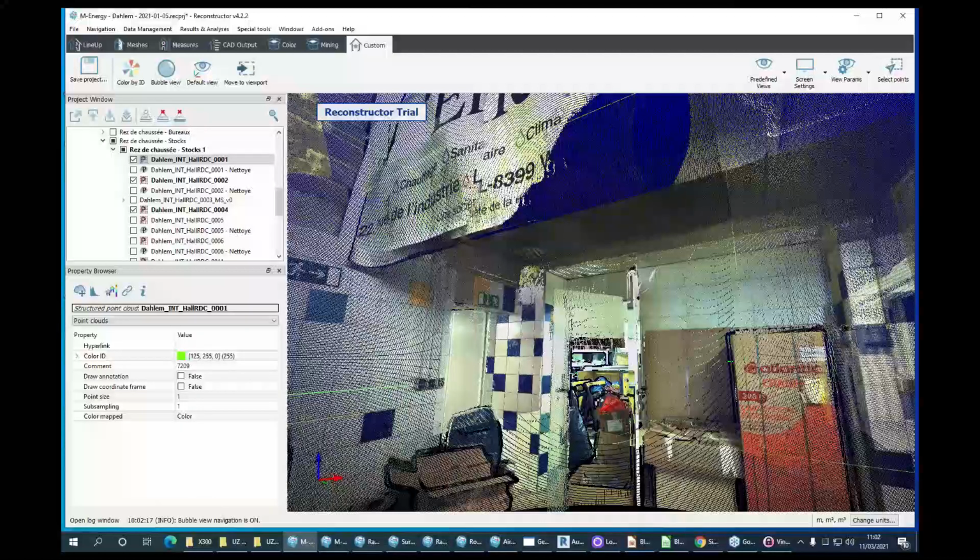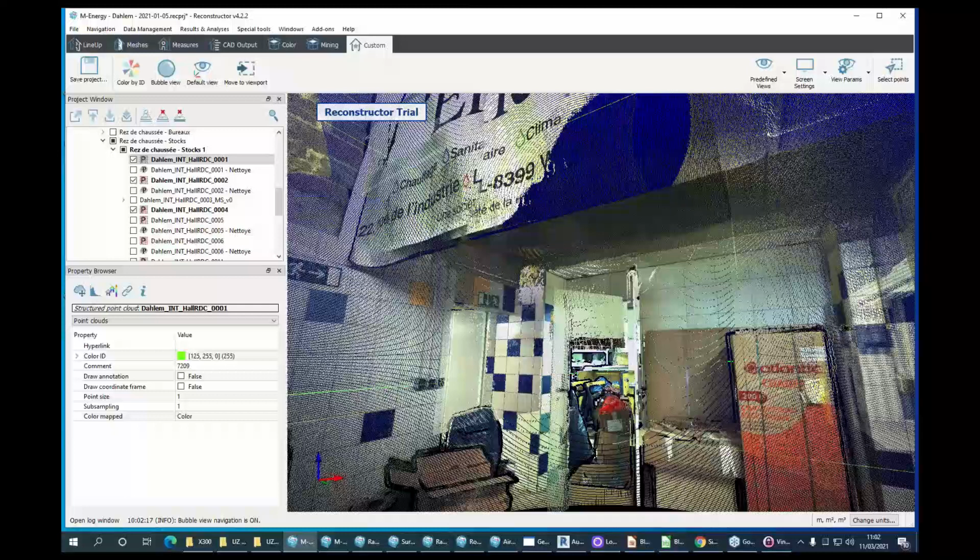Yes, very good. On some occasions where you have less communication between inside and outside, small windows, small doors, it is also useful to use a total station to build a topographic base. That is correct, yeah, so that's another option. On this customer, they tend to work mainly inside, so we didn't care much for that. The total station can be a good system, but as I say, if it works, it works. So just use something that works for you. Most of the time, just using a laser scanner was enough for us.